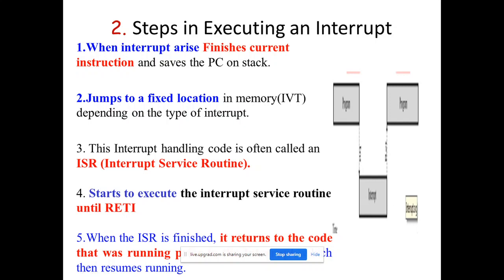At the end of this ISR, there is which instruction? RETI. When the RETI instruction comes, at that time the controller will pop the return address as well as data from the stack, and it will jump back to that location. Here 2000 we preserved on the stack. The same value comes back, and the PC is loaded with the same address, that is 2000, and the next instructions are executed continuously.